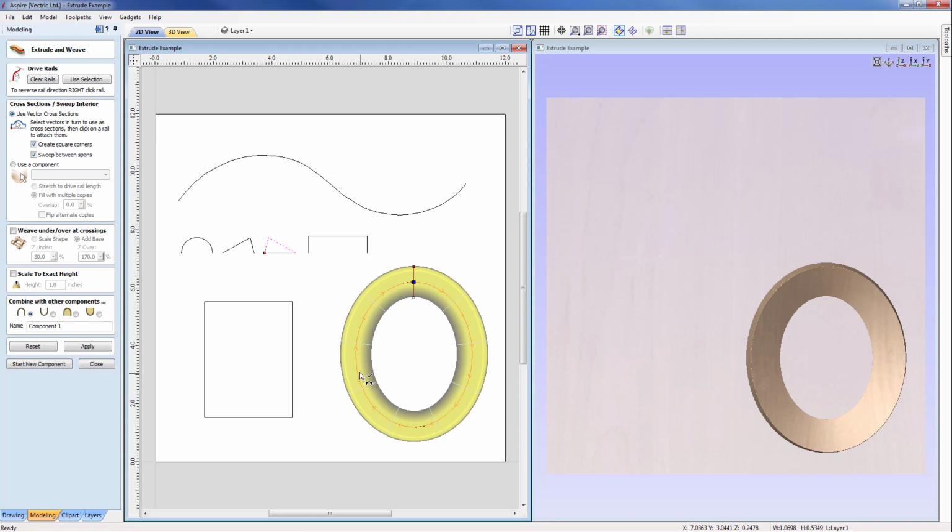Now, another thing I may want to do is to add in extra cross sections. Maybe I would like to put some rounded cross sections in the middle region, but of course one way I could do that is to right mouse key and say add to all rail nodes. Okay, or I can manually add them by hovering over the node or in any other position.